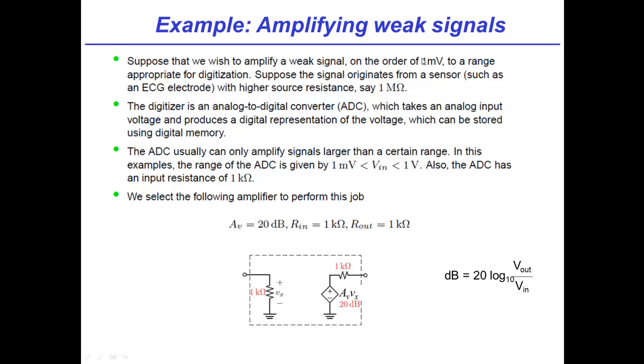And not only is that source voltage very low, but it's got a very big source resistance. What that tells you is that it can't push a lot of current, right? It's a very big RS in its equivalent circuit. And what we want to do is take this voltage that's varying over time and digitize it, because we're in maybe a hospital or something, and we want to use an analog to digital converter to record that.